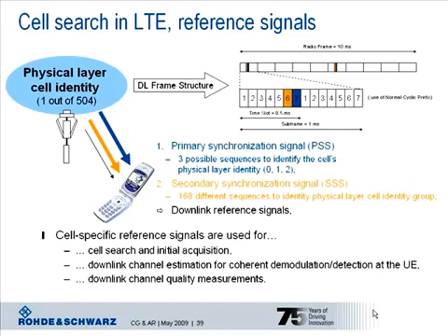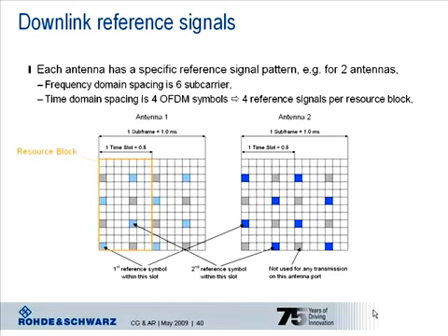In the matter of cell search, the reference signal helped the terminal to get frequency and time-wise fully synchronized. How can that be understood? Reference signals are transmitted as well-defined resource elements. A resource element is the smallest resource unit in LTE and translates to a subcarrier, respectively OFDM symbol.